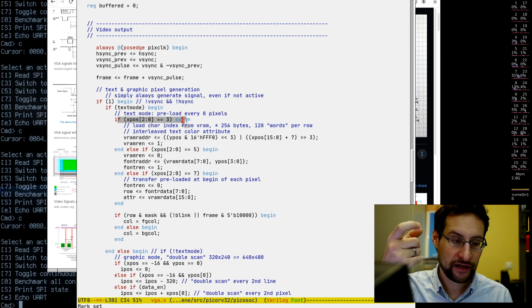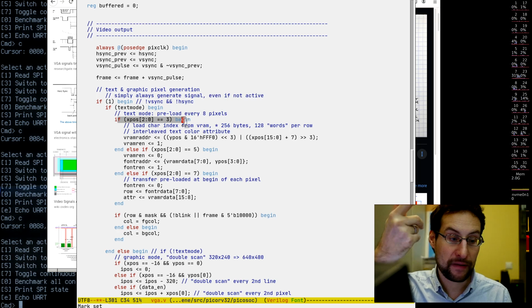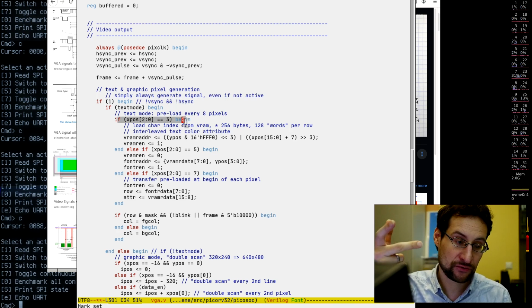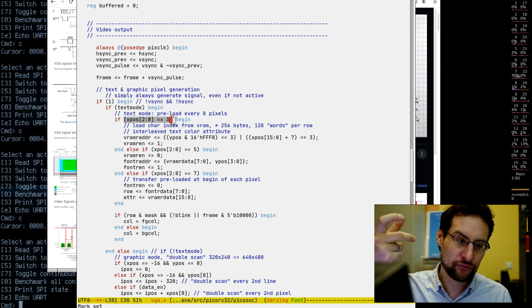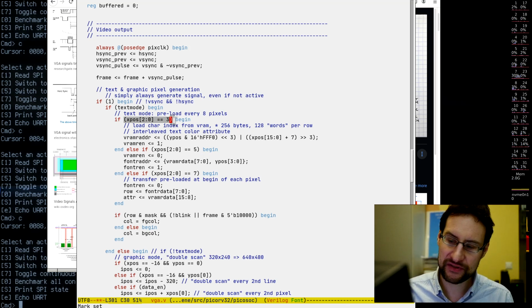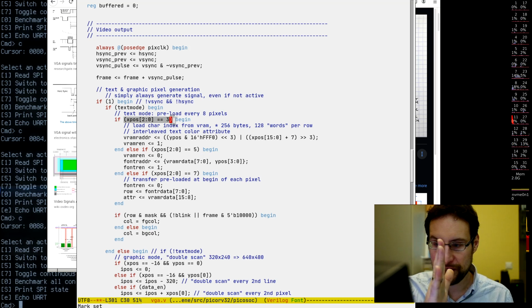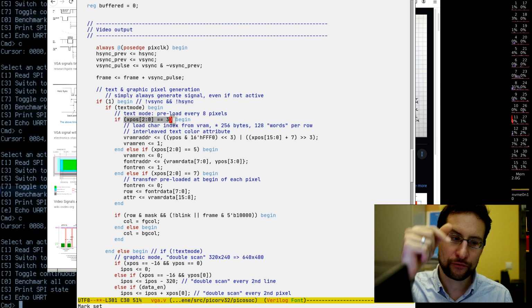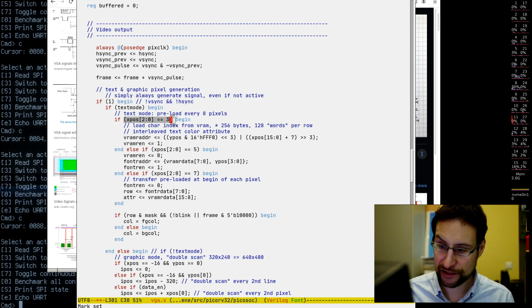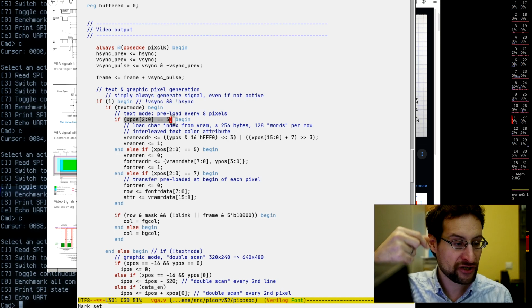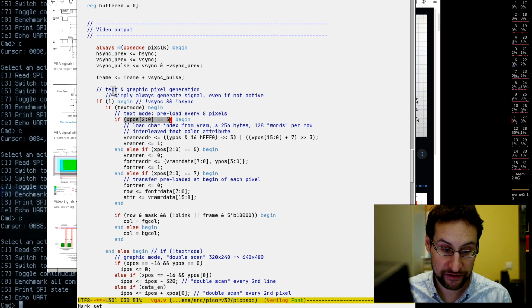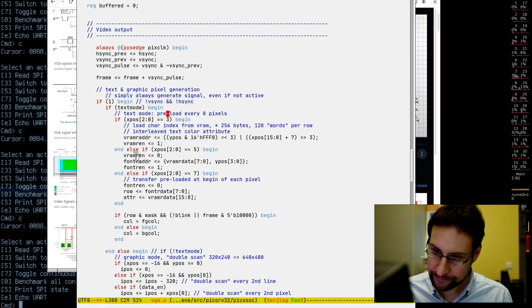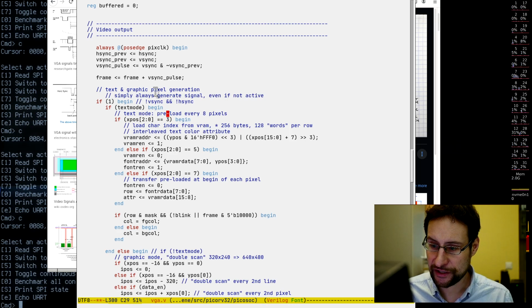Earlier I had this more open coded, as in if equal minus, for example. Then I figured that with two's complement logic it just works when we load, so we do not need to specifically code this for negative values. We have 8 pixel clocks for the 8 pixels of each text character cell, and we preload exactly in the middle of the cell, at clock 3. There's a reason for that, coming to that in a moment.